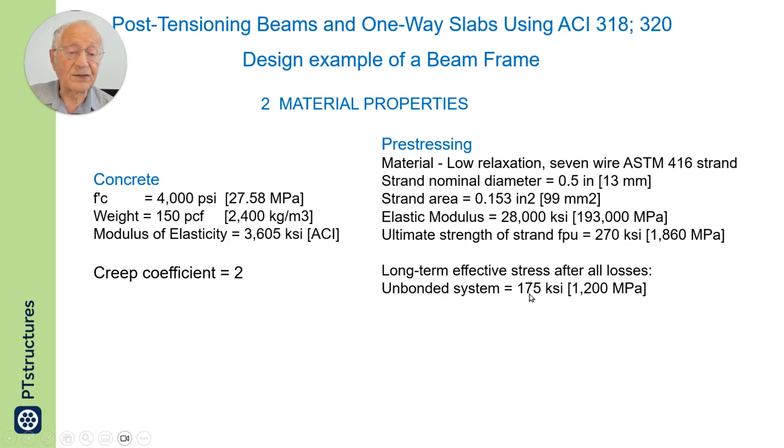So I assume that after all the losses have taken place, the stress in the strand will be 175 KSI, and I use this 175 KSI for the design.